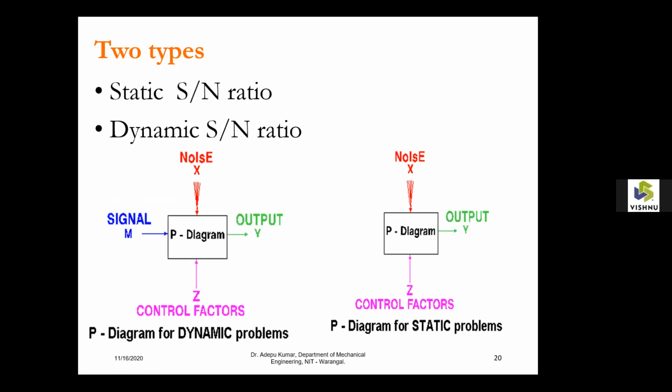Whereas if you take the casting process, the dynamic system is not useful, because casting takes a lot of time to get your final component. If you want to change the system, then everything has to change. For changing itself, it takes a lot of time in a conventional manufacturing process. If you take additive manufacturing, you can change dynamically without much loss of time.